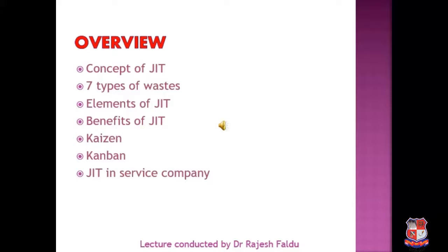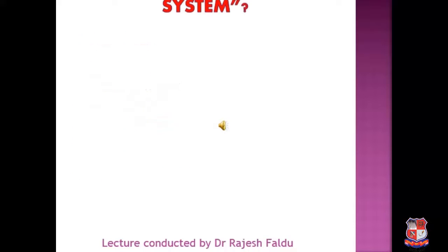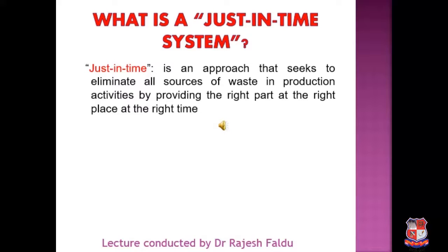In today's session, we are going to cover the concept of JIT, 7 types of waste, elements of JIT, benefits of JIT, Kaizen, Kanban, and JIT in service company. So let's start our session by understanding what is JIT or just-in-time or lean manufacturing system.